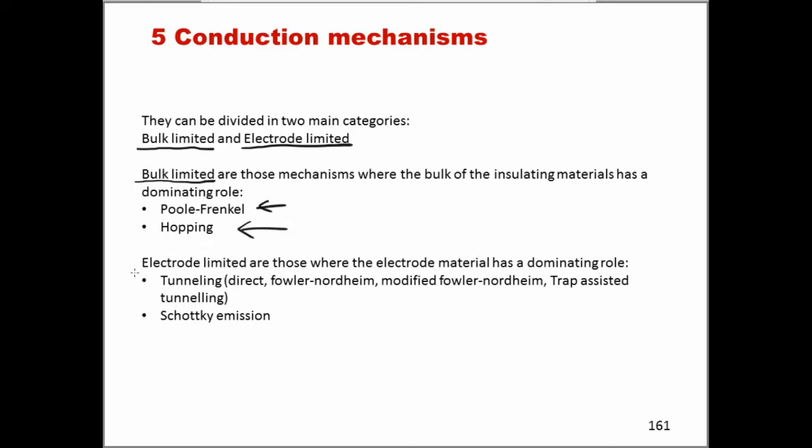The other category is the electrode limited conduction mechanisms, where instead the electrode is very important, or maybe the relative position of the Fermi level of the electrode as compared to the semiconductor or the insulator that the electrode is in contact with.